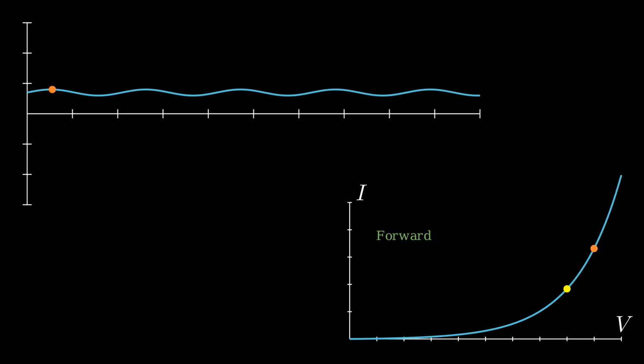When we turn the AC signal back on, the operating point moves around the Q point. As long as the AC signal doesn't move too far from the Q point, the tangent line at the Q point makes an acceptable linear approximation. Unlike large signal analysis, small signal analysis for a diode has the diode operating in a single region.